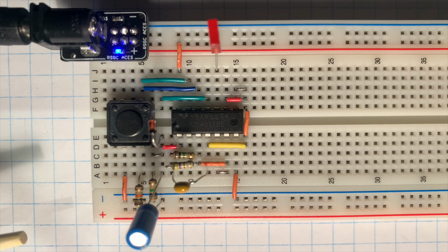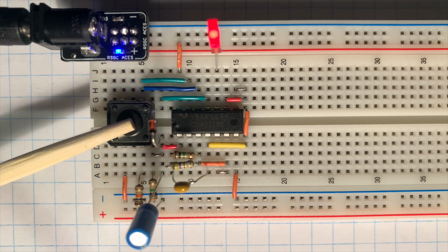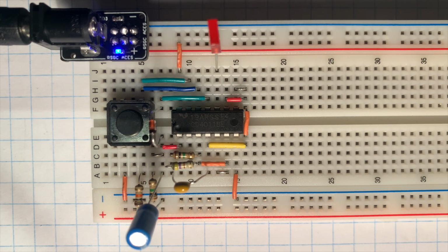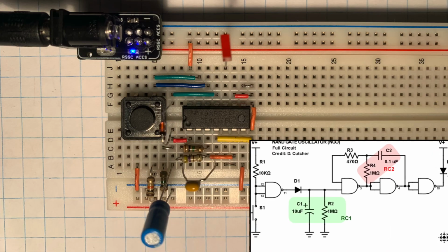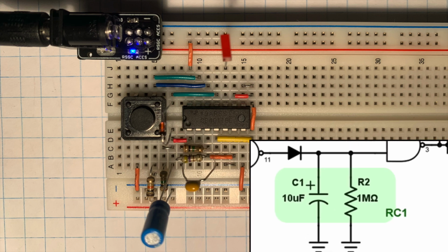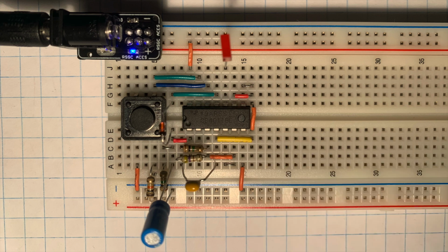This next step adds a NAND gate oscillator to the analog button input. This circuit creates a clock signal output when the button is pressed. The clock signal consists of a high and low frequency. The duration of the clock signal can be changed depending on the resistance or the capacitance in the RC1 section of this build. The higher the resistance or the bigger the capacitance, the longer the duration will last.